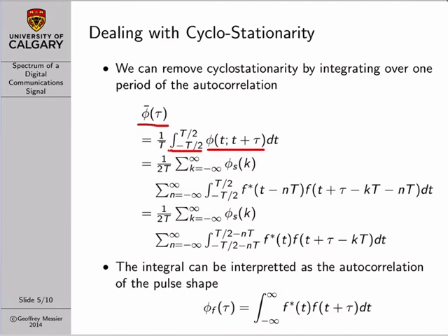And so then the next expression, which gets a little bit more complicated, is I'm going to take the expression for our autocorrelation from the previous slide and plug it into this integral, right? So out front, we've got the summation of the autocorrelation function of our signal vector.